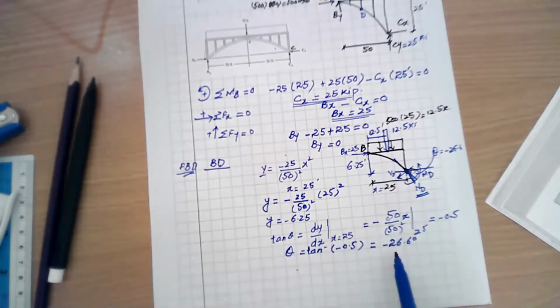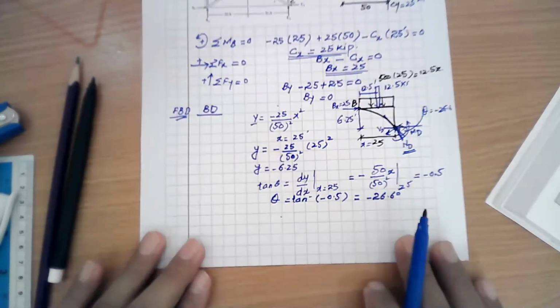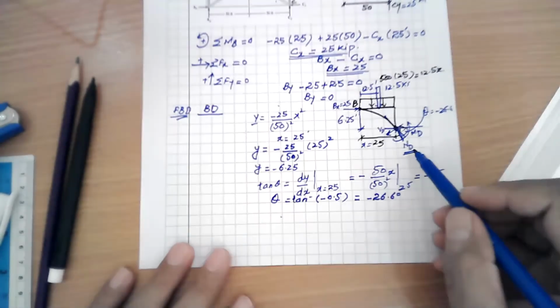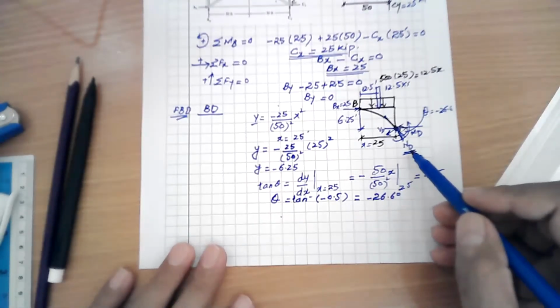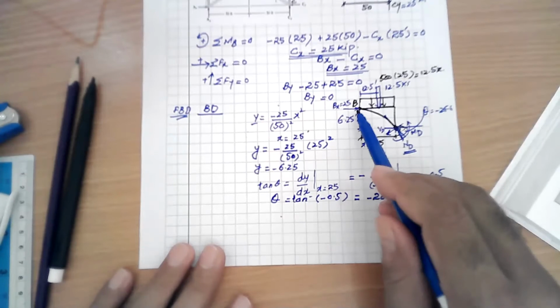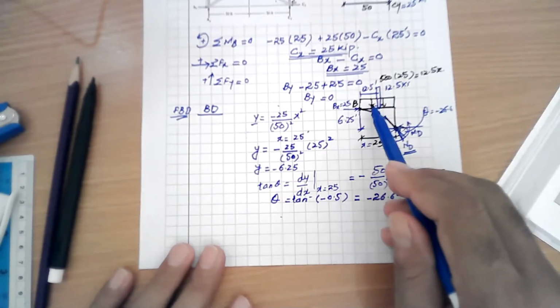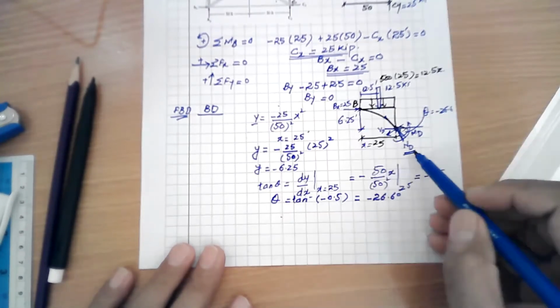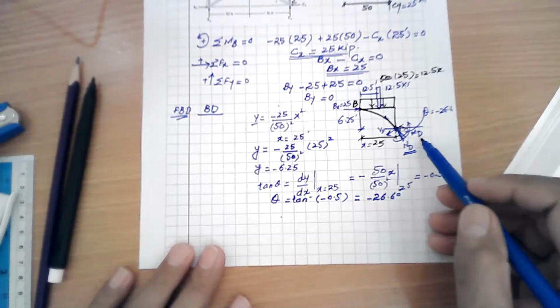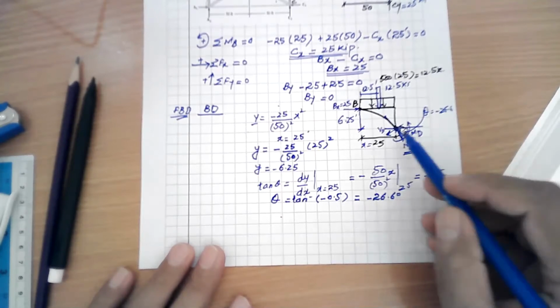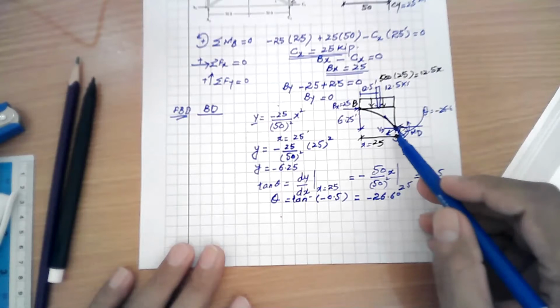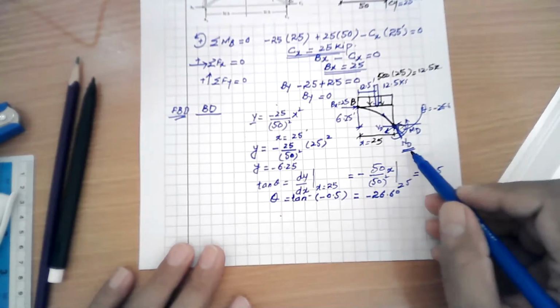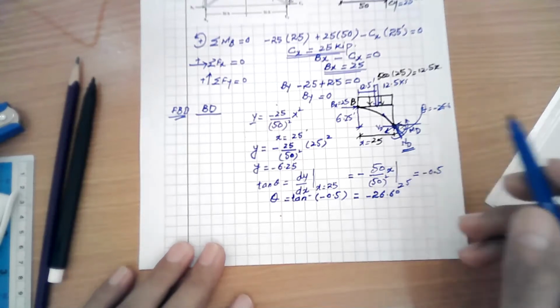So once you calculate the theta, now to calculate the unknown, which is ND, we have the reactions and the loading at this point. The unknown is moment at point D, then the shear force at point D, and the normal, which is axial compression force to the arch.